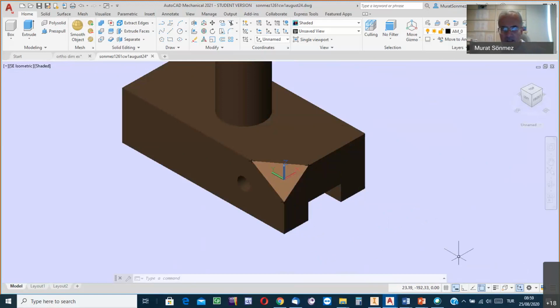If it is on, and you're going to create the rectangle by inputting its width and height values, see in the simulation whether the rectangle is in the correct direction, ready to be created. Just write the width and height values as absolute values; it does not matter whether the width is at the negative side or positive side of the coordinate axis.